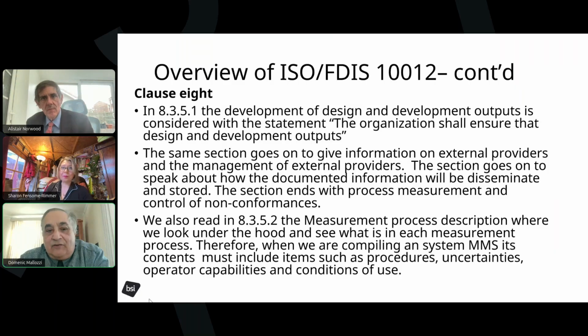I mean, the classic discussion is how to calibrate a torque wrench in the cal business, and we all have the little click type torque wrenches in our labs, and somebody grabs it at one end, somebody grabs it at the other. They change the axis of measurement. The new standard on that, Dom, is you put it into a machine, hit the button, and it does it automatically for you now. Yeah, I'm familiar with it, but again, there's still companies applying the wrench that have the problem of people using it correctly. Using it is the biggest problem.